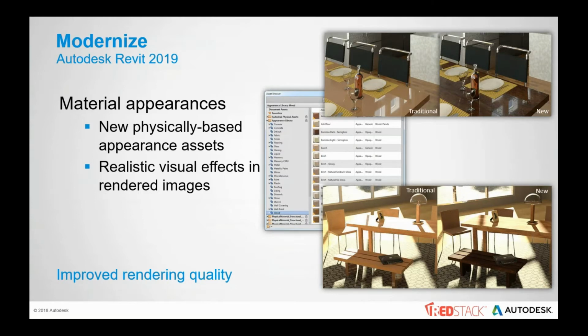With material appearances, you can create higher quality renderings with a collection of physically based appearance assets in Revit 2019 that take advantage of the physically based Autodesk Ray Tracer rendering engine in Revit. These assets provide high quality, realistic visual effects in rendered images and views that use a realistic or ray traced visual style. While not all assets in the provider libraries use the physically based appearance assets, a large collection is provided, including carpets, ceilings, stone and concrete, glass, roofing, wood, and more.